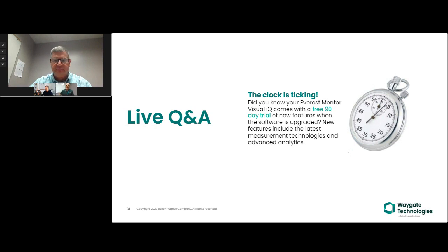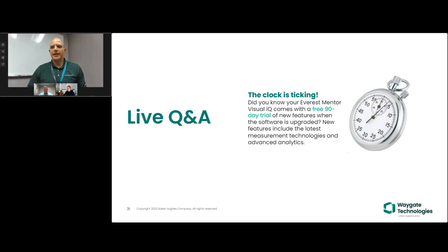Sure. Yes, this is a common question that we get a lot. And unfortunately, there's not a simple, straightforward answer to it. Under the best case conditions, if you're up really close and following the guidance we've provided, you typically can get repeatable measurements to within roughly one thousandth of an inch, which I believe is about 0.025 millimeters. But it really depends on the measurement application, the surface finish, and the techniques that you use.